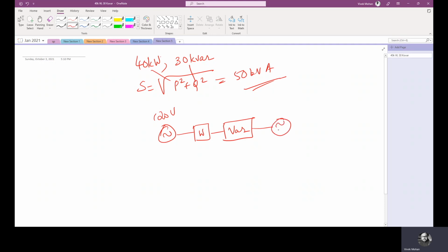So I'm writing this as AC motor. The wattmeter indicates 1800 watts and the varmeter indicates 960 VAR. Now you are asked to calculate the in phase and quadrature components IP and IQ.